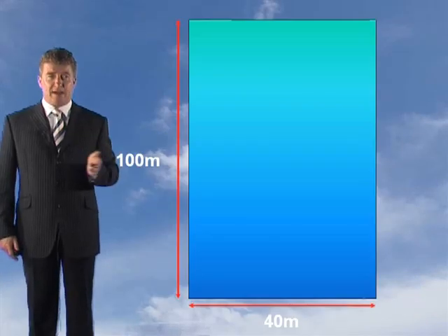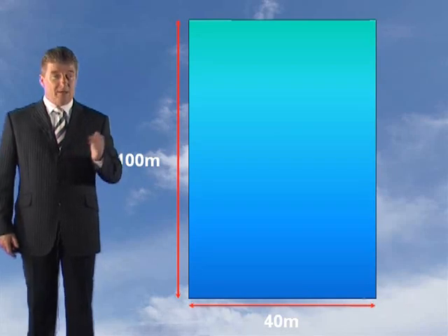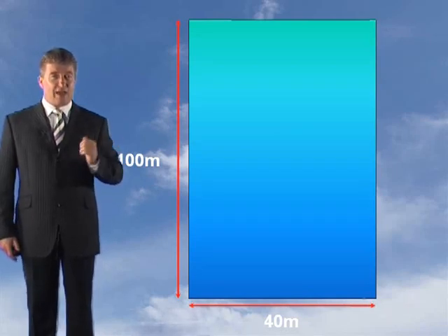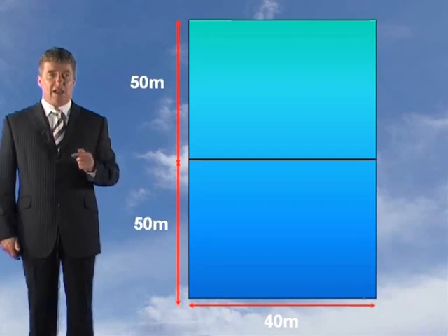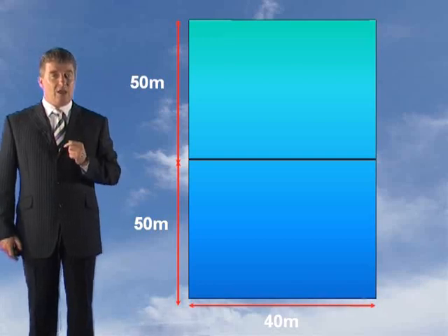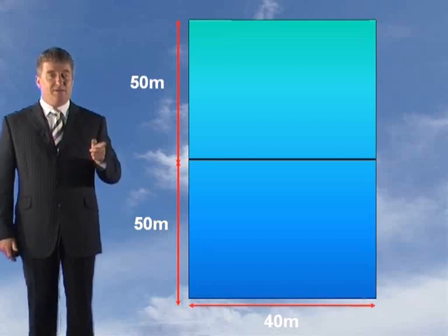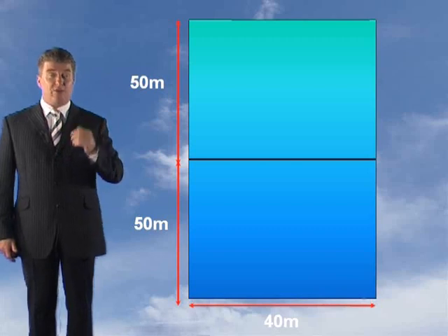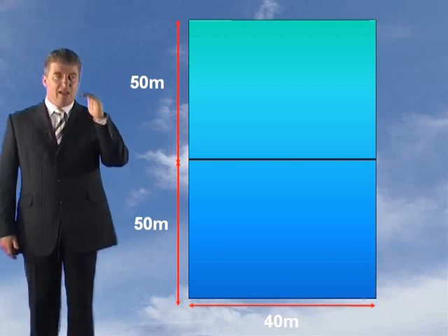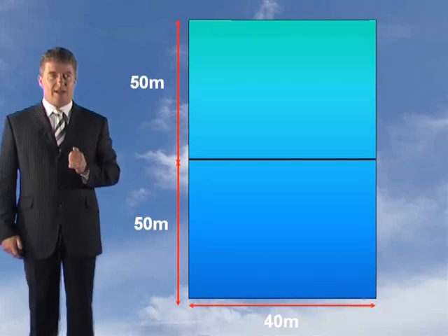So let's look at our warehouse. The building is 100 metres by 40 metres. And again, the maximum size of reservoir is 2,000 square metres, as we said. So clearly, as you can see, we can get away here with 2 reservoirs, 50 by 40, which gives you 2,000 square metres for both. Based on that design, that's what you'd have, 2 reservoirs.